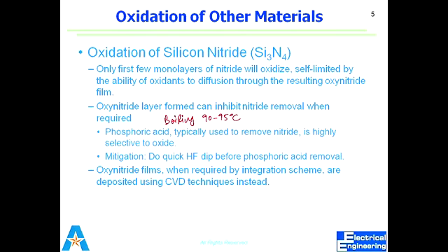So here the use comes in. That oxynitride does not permit the nitride under it to etch away. It actually behaves like a mask. So it's a passivation layer. Yeah, it's a passivation layer. So if I want to use it as a mask, I can.